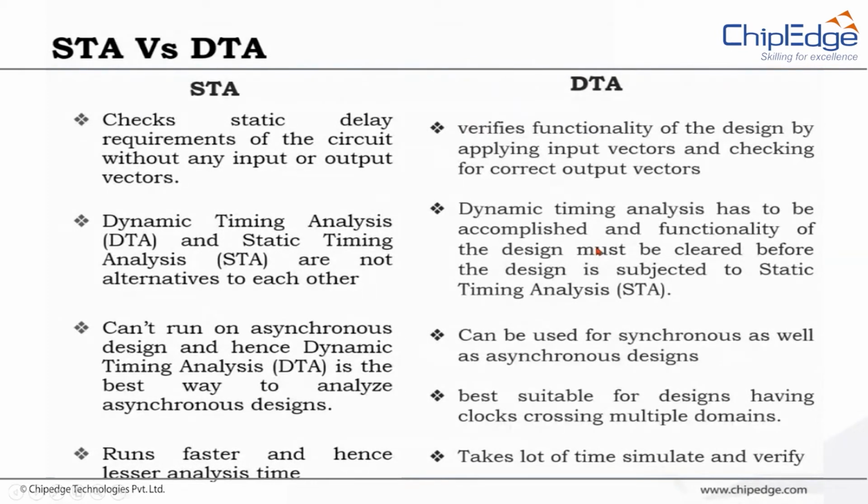Okay. As long as there are asynchronous paths in the design, STA is trying to put a false path on them, right? Now, what about the timing requirements or functional time requirements on your asynchronous paths? That is where the dynamic timing analysis plays a very big role in giving us an idea about it. So, it is very much suitable for designs where you have a lot of asynchronous paths, which you need to see how well they are behaving or how well they are passing from one part of the circuit to another.